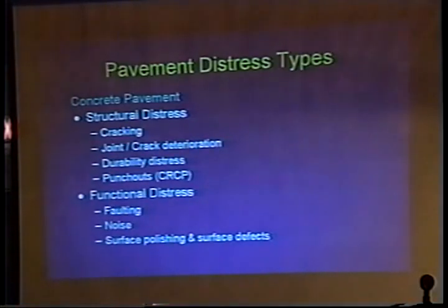Of course, for concrete pavement, there are several different distress types. More of the structural problems would be the cracking, where you don't want to have the cracks happen. Concrete does crack. Eric said what he said was true. The longest that the slab is going to be is the day that it's been poured, right after it's been poured and in place. From that point on, as the heat of hydration goes on and it loses some of its moisture, it's going to shrink.